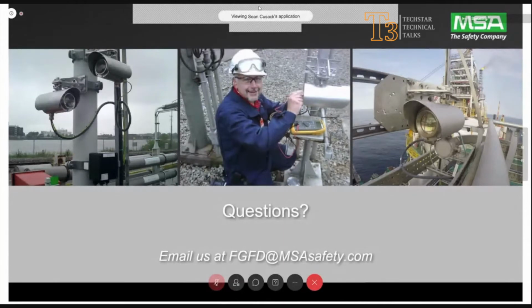You mentioned the ability of the unit to detect methane and H2S. Do you need 2 units to accomplish this? Yes, you can do it with 1 unit, and it has two 4-20 outputs. You'll have one 4-20 for methane and one 4-20 for H2S, or if you chose to go in a direction where you can utilize two, you can use two. So you can use one dedicated for each, or you can use one for both.